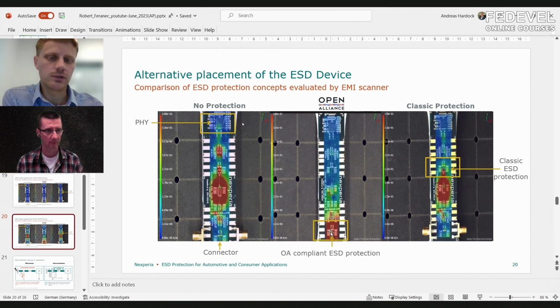So you see a lot of current close to the connector. Everything is basically discharged in this very small area close to the connector. You protect everything: the PHY, the common mode choke, the common mode termination. So everything is protected here. This is a big plus, so you can be more flexible with the selection of all these peripheral elements, the resistors and common mode chokes, when having this position. Okay.